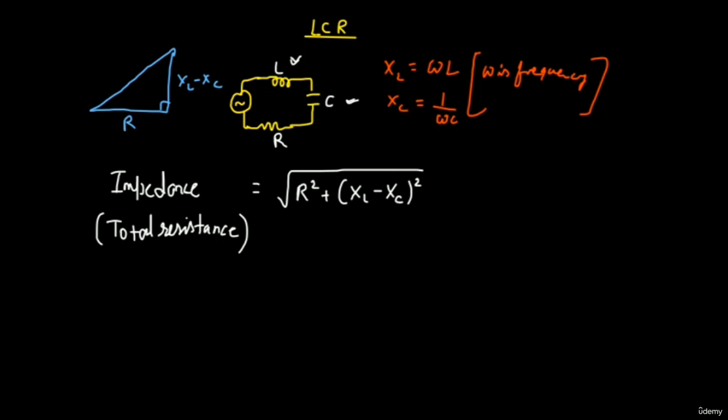Okay, let me highlight which line I am asking about. What is this line going to represent? Well, can you say that? Say it loud so that everyone will understand. Okay, just by using the Pythagoras theorem, what we get here is the resultant, and that resultant is actually R square plus XL minus XC to the whole square. Exactly what we have written here.